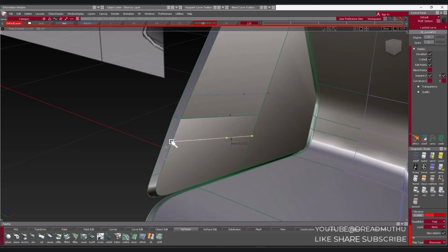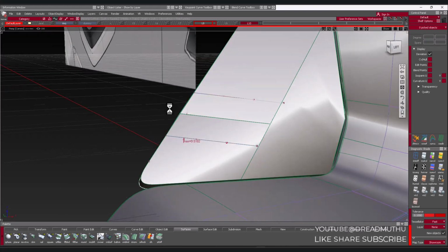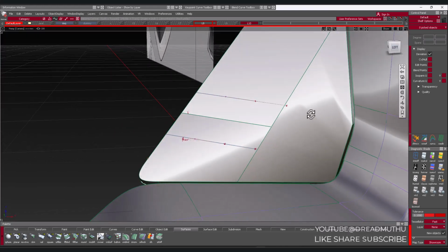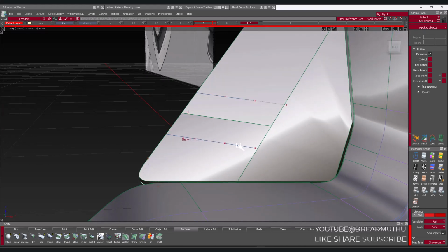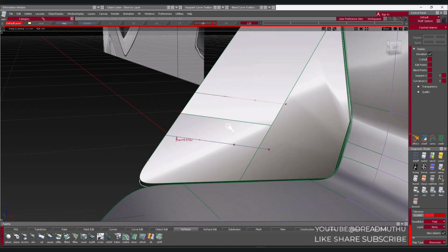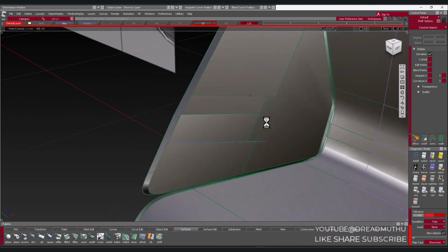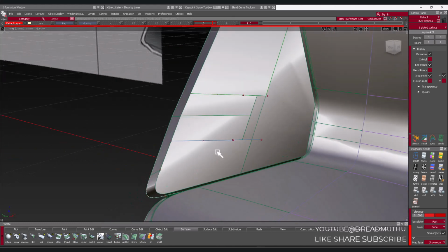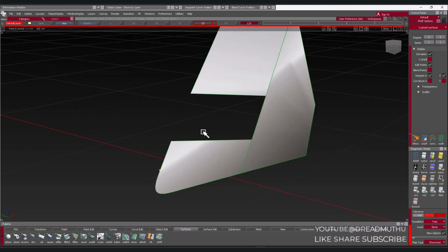Yes, okay, and then we'll extend this, project these two surfaces, trim, yes, okay. So we'll select these 3 surfaces first, hide and select, blend, square, edit, make curvature. Then 3 we need position, and select explicit. We'll go for 5.